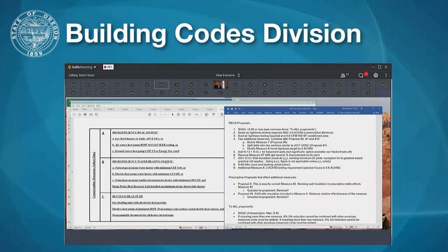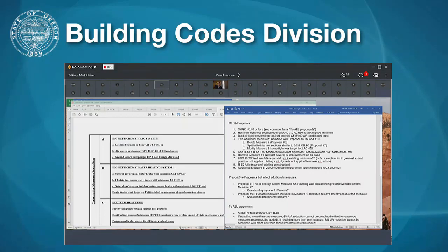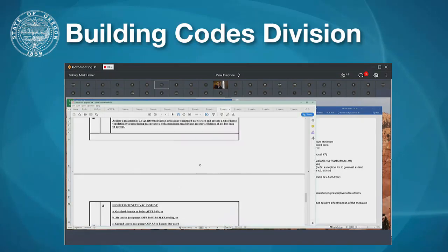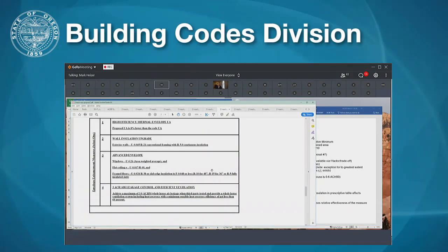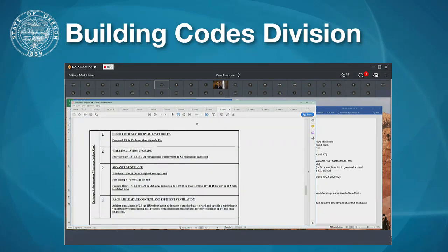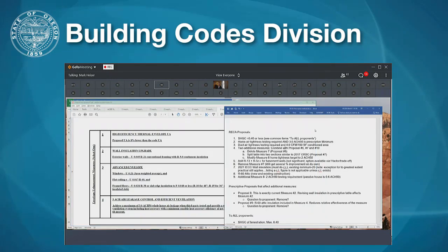And of course, you adjust the envelope to, I believe, 2 ACH 50 testing for one of your tables, a tighter air change target. That was one piece we were hoping to get out for discussion, some of the general differences, as we're moving toward that ZERH target, tightening up under a REACH code for better home air sealing.